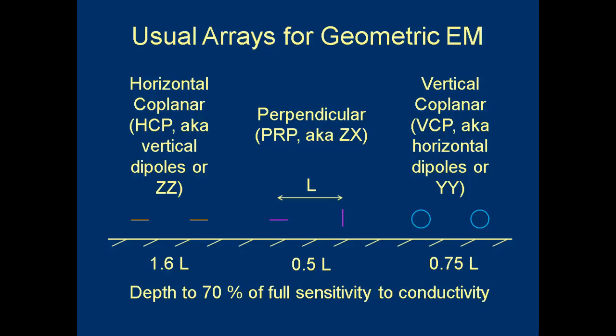The transmitter and receiver in geometric electromagnetic induction instrumentation are coils of wire wound circumferentially about an axis. The coils are separated by at least several coil diameters, so each can be treated mathematically as an oscillating magnetic dipole coincident with its axis.